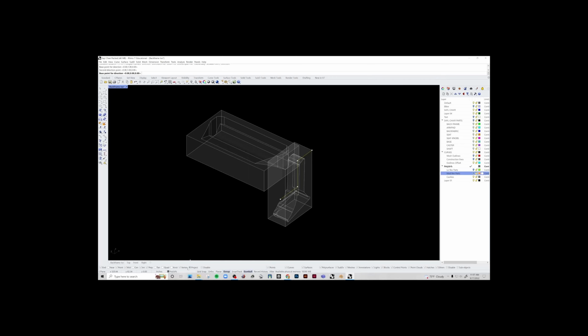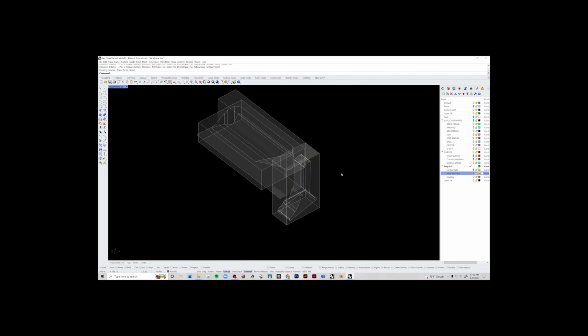Oops, I have to turn off my project. And you'll see it'll start to go in that direction that you set. But I want to go this direction. And so we'll select that, and then we're going to use split, a Boolean split, and select the surface. And we'll do the same thing for this guy.